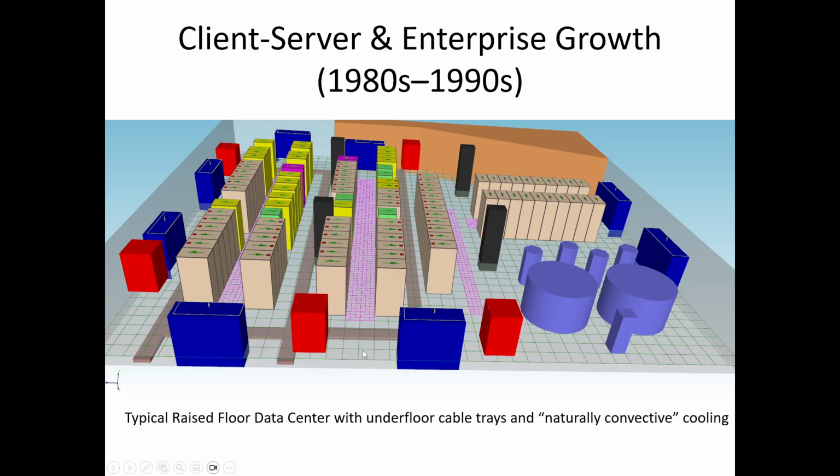The floor should be sealed, but you do run into leakage in these designs. Furthermore, the rack equipment is awfully close to the cooling units. You see that on this side of the room. See a little of it right here too. This tends to cause problems because the velocities underneath the floor are high in this region.